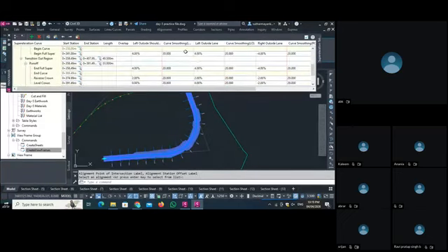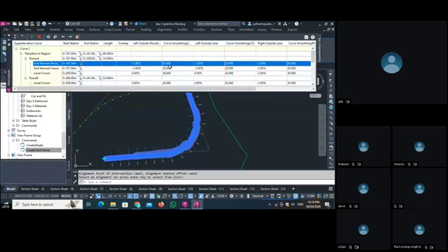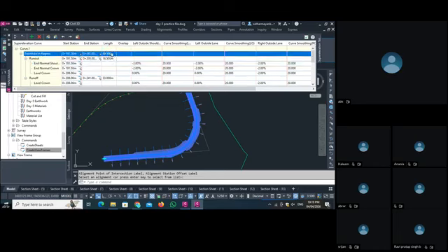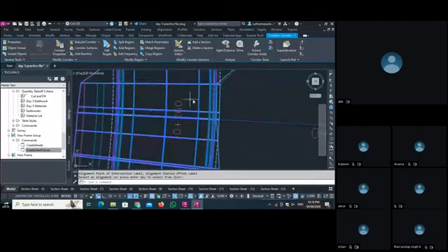So as this one is all set, then you can click OK. If you have a problem here in the curve smoothing or whatever, you can change your length. As you change your length, your smoothing is changed. If there is a yellow mark here, you can set it by the trial and error method. As I click OK, my super elevation is created on this part.